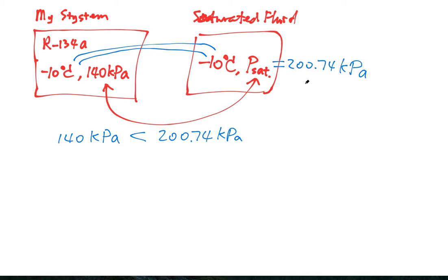However, here my system's pressure is lower than the pressure of a saturated fluid system at the same temperature, so my system must be a superheated vapor system.